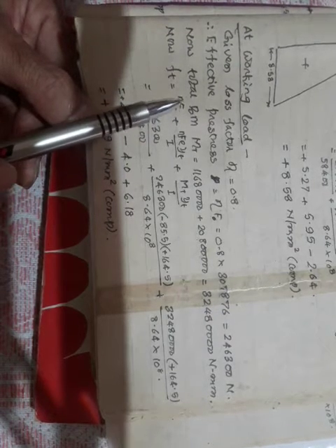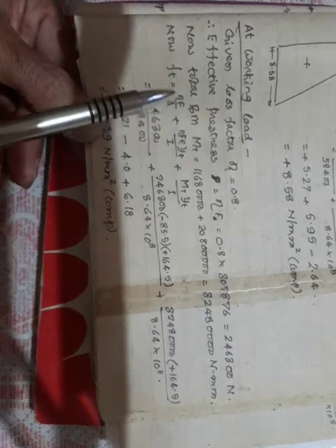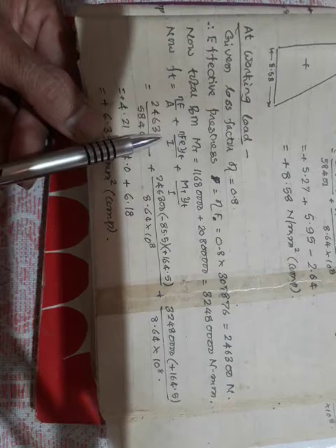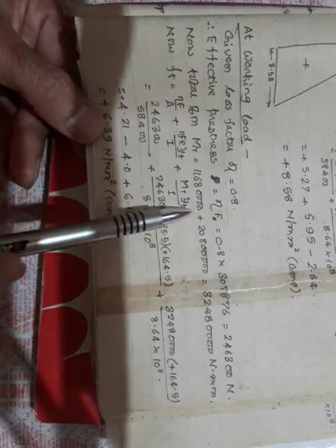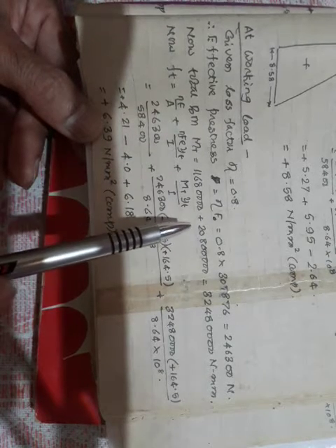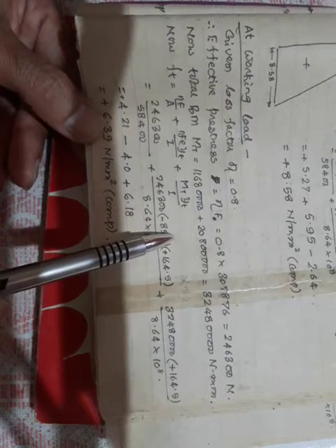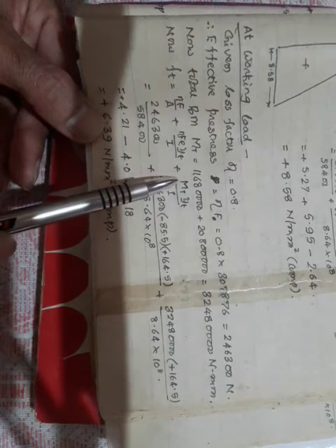So now you can write the top fiber stress Ft is equal to eta F by A. It is not F simply. At the working load, your pre-stressing force has undergone some loss, so it is the effective pre-stress, eta F. So eta F by A plus or minus eta F e Yt by I plus or minus Mt Yt by I, because now the live load also acts on the beam. It is Md Yt by I plus or minus Ml Yt by I. Otherwise, I can write directly Mt Yt by I.